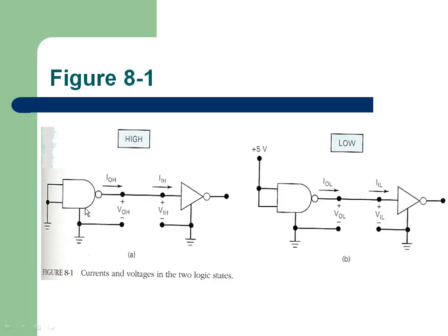A simple arrangement: a NAND gate is driving a NOR gate, and the NAND gate output is a voltage level called VOH. The word O has been attached here because it is the output of the gate, and the word I is attached here because it is the input of another gate. High is used because this gate is driving a one, and this gate is receiving a one.